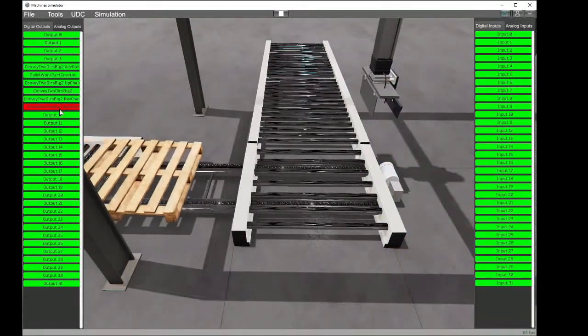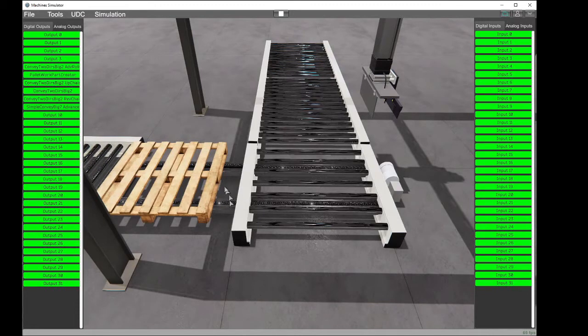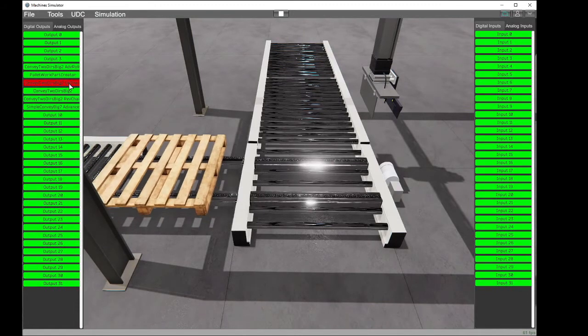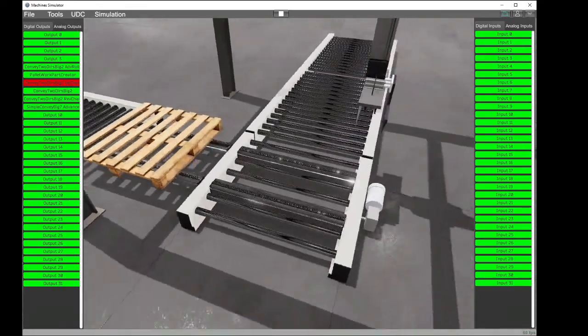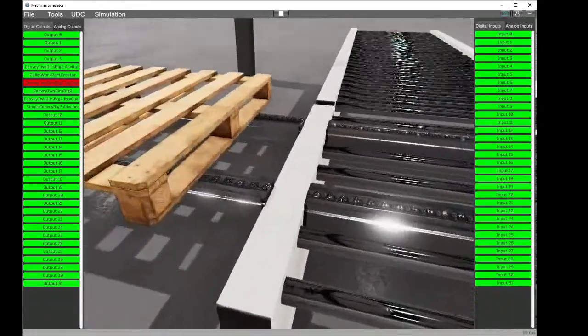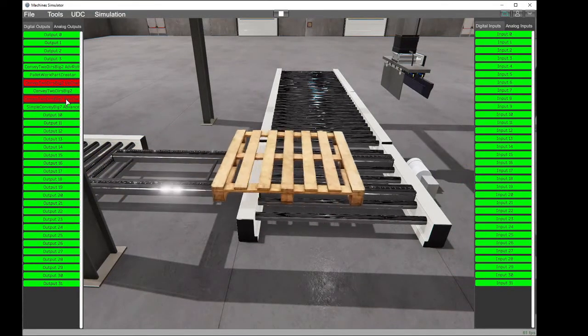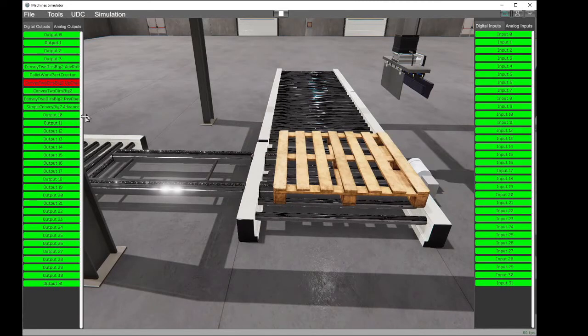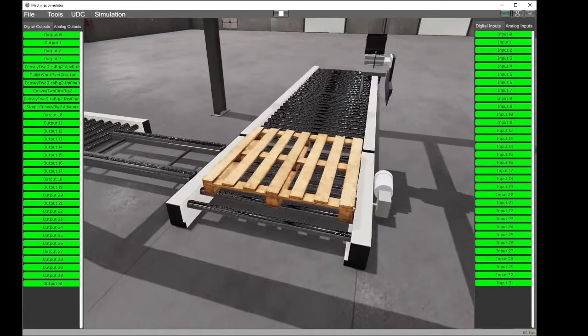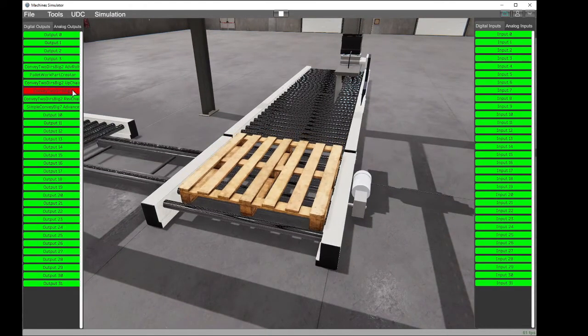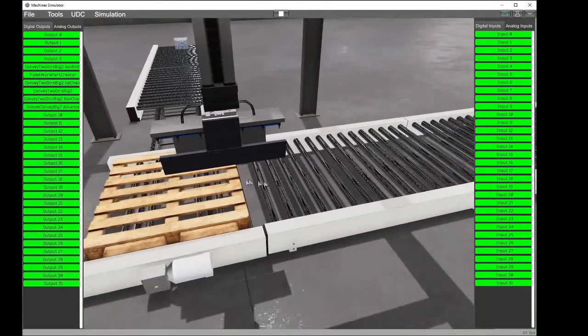the conveyor advances, the pallet arrives to the chain system. We must elevate the chains. Okay. The chain has gone to the upper position. We advance the chains, and now we can move down the chain system. Then I must activate this PLC output. Okay. Now I must connect the conveyors, the roller conveyor from the 2 directions.